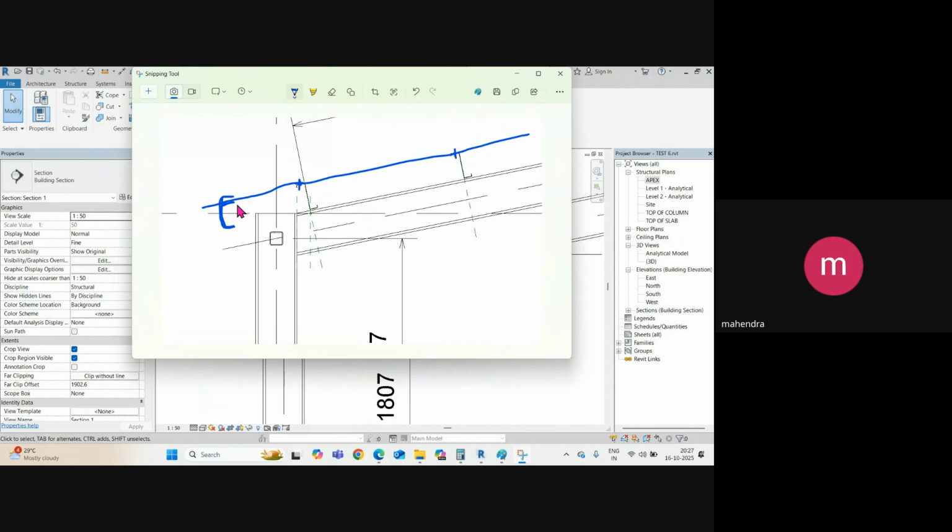But you may think how to connect this end purlin, because it looks like it is just in the air. So in that case we will provide the detail like this. We will add one plate here. So this is just the end purlin, right? And this is my column here, right? So in that case what we need to do, we need to add a plate here.